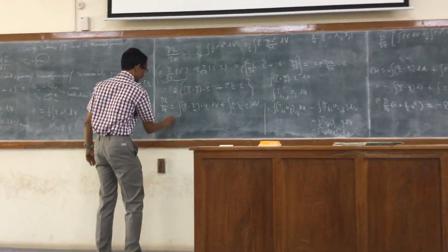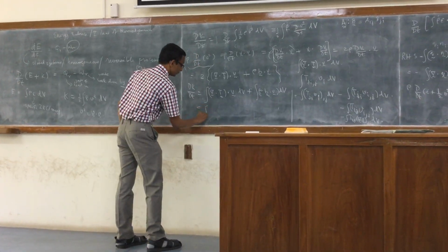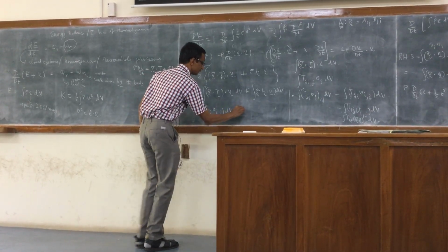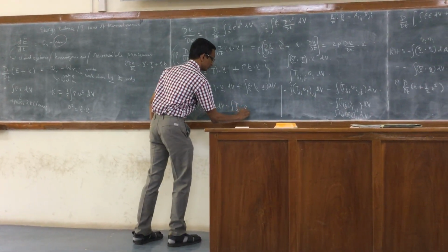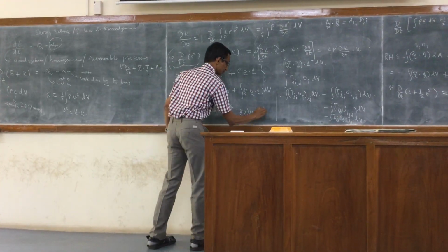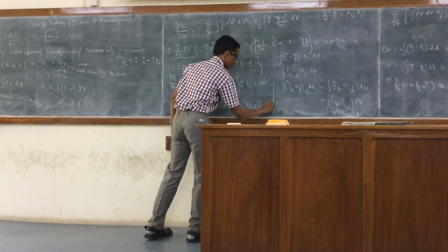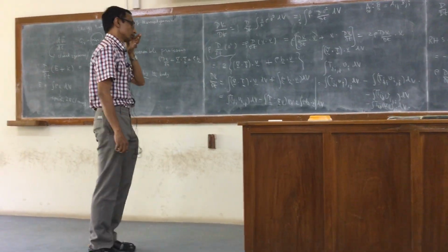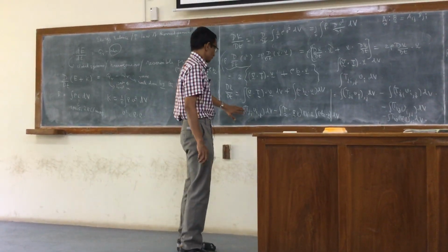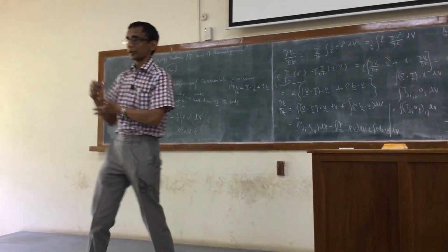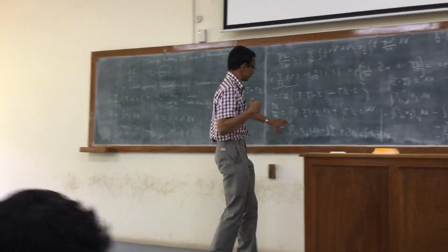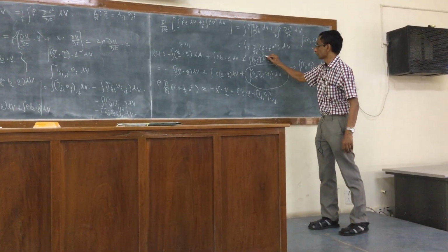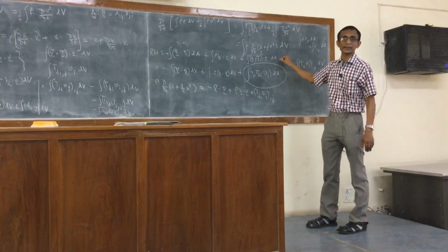So finally, I can write dK by dt as the integral of d_ji B_i comma j dV minus the scalar product of T with the velocity gradient tensor plus, now, if you look at this, clearly, if I want a physical interpretation of this, because sometimes the volume integral is useful to get a local balance, but if I want a physical interpretation, you can clearly see that this is T. What I have here is exactly T dotted with v dA, right?